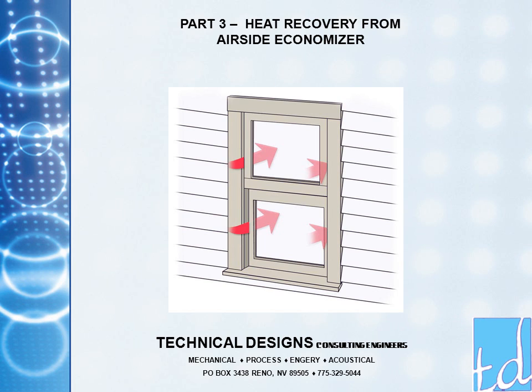In the classroom wings, we use this conditioned air to heat and cool the hallways. Transfer grills in selected lockers move the air between the classroom and hallway, eliminating the need for additional hallway cooling units. Effective building and space pressurization control not only ensures proper distribution of conditioned and ventilation air to the space, but also can confine odors and contaminants to specific areas of the building.